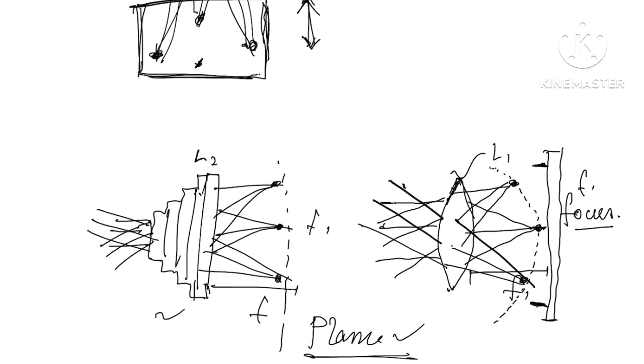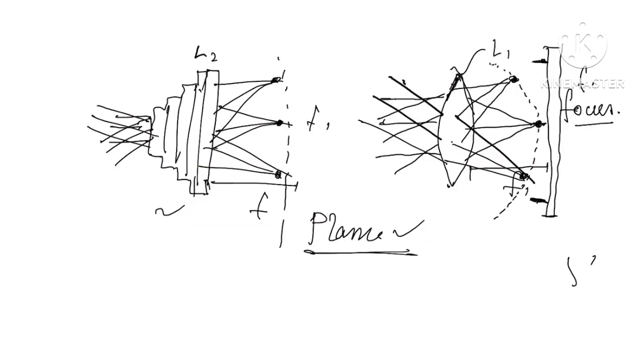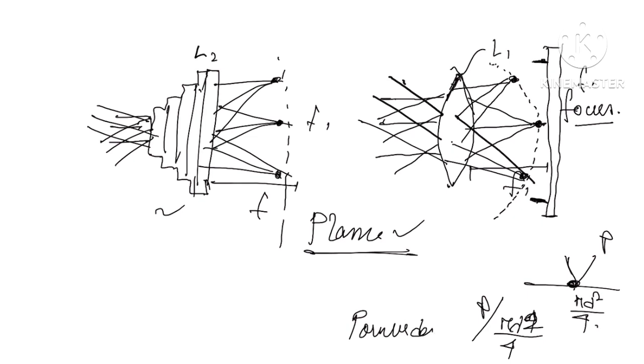focus position. And we all know the main and important thing about laser metal deposition is its energy density. How much energy or how much power we are getting per unit area. This is the focus spot, so pi d square by 4 is its area. So the power density is power by unit area. And this is the main thing in laser metal deposition, and we need to ensure that at every position over the build plate, this power density should be constant.